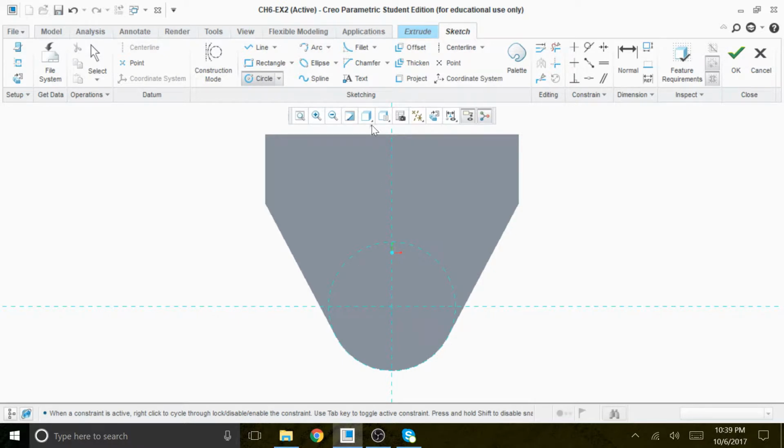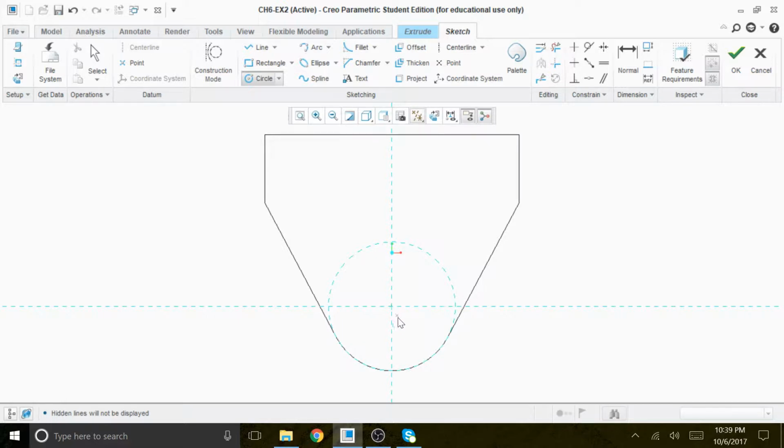See it, this is, let me just turn off the shade, and we have no hidden. See that? And the cursor is going to snap to the center of the circle. Okay, then when you stretch that, watch this very carefully. As soon as you get close to the existing curve, it's going to say R equal R. Okay, see that? R. So watch for that. Don't go over it. Just as soon as you see that, then you say I'm happy. So R1 equals R1.